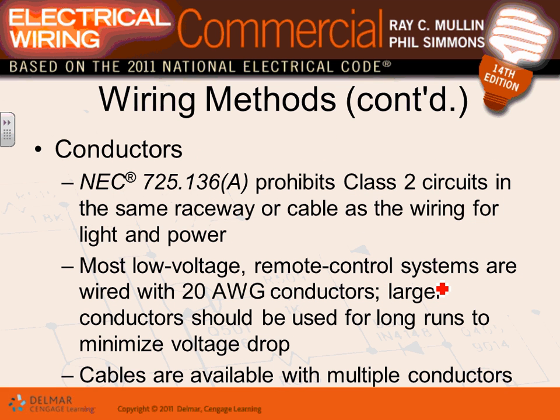The conductors that they use, guys, for the low voltage are called the class 2 circuit. Class 2 circuits can use a gauge. Typically, they are gauge 16, 18, or 20. These are the ones that they use. The only time, Derek, they use higher gauges like number 12 is for voltage drop.